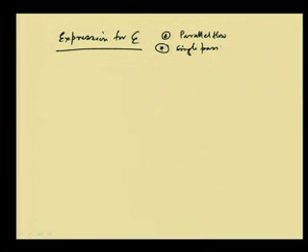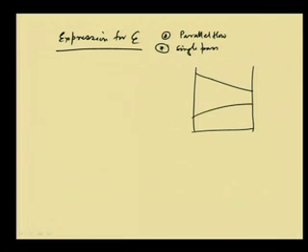Okay. Now, to do that, first we will again draw the parallel flow situation, whatever we have drawn already. So, if this is the case, here it is TH1 and this is TH2. Okay. So, this is the parallel flow situation. Here is the area of heat exchange. This is station 1 and this is station 2. This is TC1 and TC2 is the outlet temperature of the cold fluid, and take any differential.